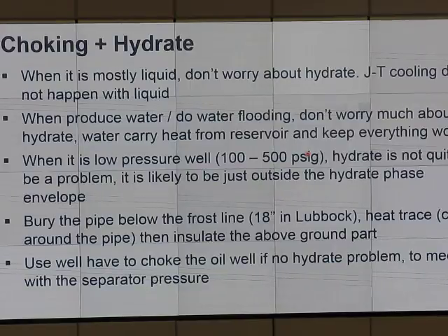Of course, sometimes, let's say hydrate temperature is at 60, sometimes you go below 60 and you may worry that you have hydrate, right? But probably not if you keep it flowing. You bury the pipe. So look at this. Bury the pipe below the frost line, below 18 inches or 2 feet.